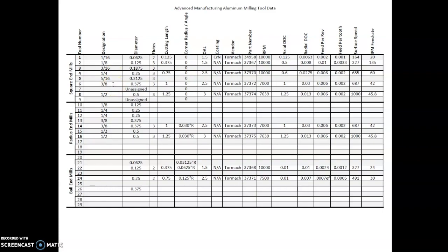So when you are using tool number 4, you go, oh, yeah, that must be a 1/4 inch diameter or something. And we tend to follow that structure as we go through, although not in all the cases. But we try to make this as organized as possible, because there's a lot of information here. So you have some designation for the tools. These first ones are all square corner end mills. We have these radius end mills. Actually, there's only 2 of them that we have all the data for. Those are the 2 that we actually have in stock.